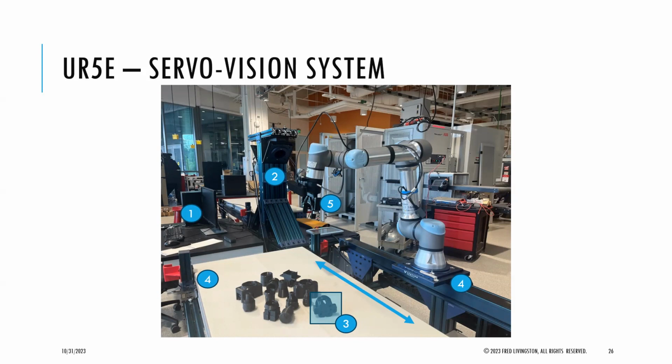So the camera is here, detects this guy here. And we physically mount that camera on the robot, so there's a fixed mount. So we know the length there. Remember, the solid is known and the dotted is unknown. And so I'm looking for this object with respect to the base. So that is an unknown to me, and that's going to be called the origin to the object there. And so what is that transformation?